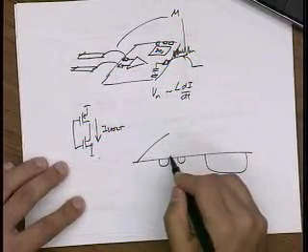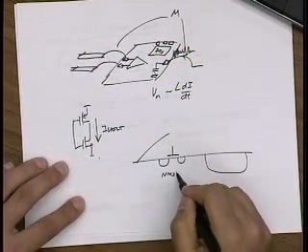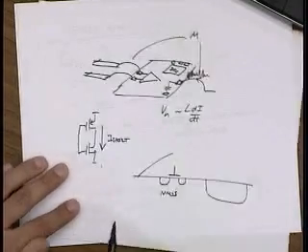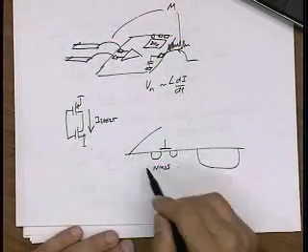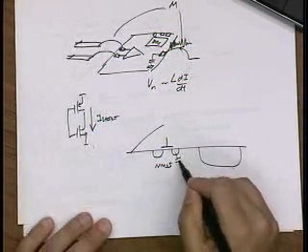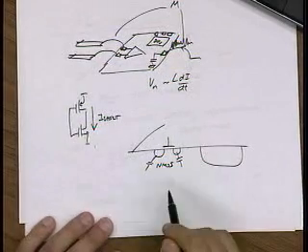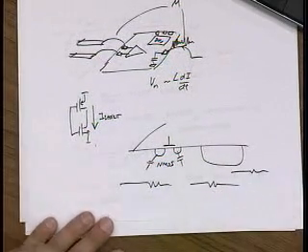Just to remind you, if this is an analog NMOS, it is actually exposed to the world. It's almost like this NMOS is sitting right next to the freeway, and every truck that passes by makes it shake, because it has these capacitances, and this substrate is like an international freeway shared by everybody.